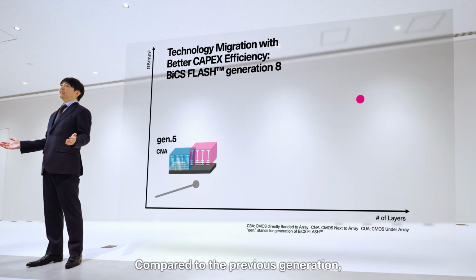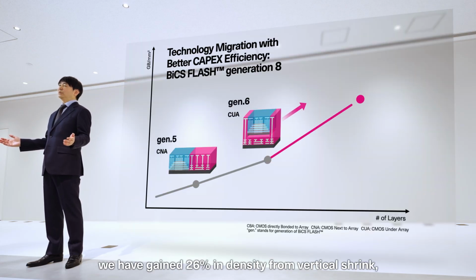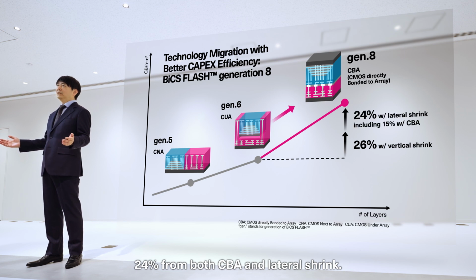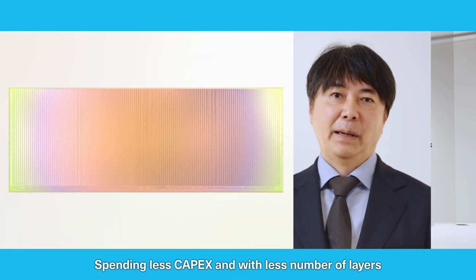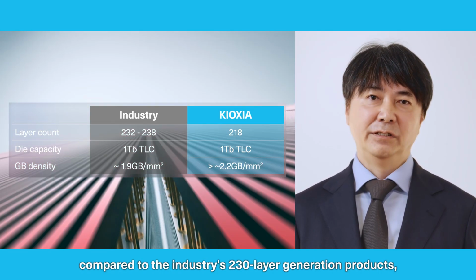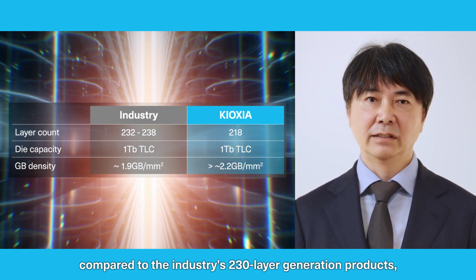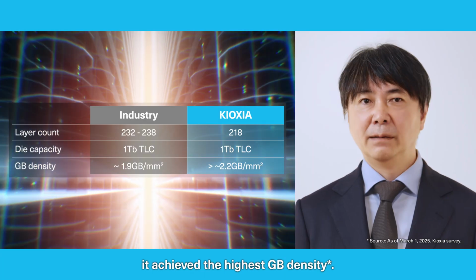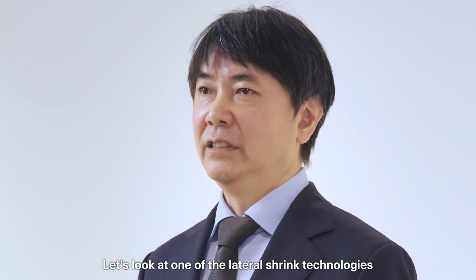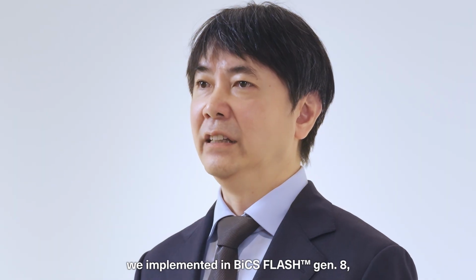Compared to the previous generation, we have gained 26% in density from vertical shrink, 24% from both CBA and lateral shrink. Spending less CAPEX and with less number of layers compared to the industry's 230-layer generation products, it achieved the highest gigabyte density. Let's look at one of the lateral shrink technologies we implemented in BiCS Flash Gen 8, which is CBA, CMOS directly bonded to array.